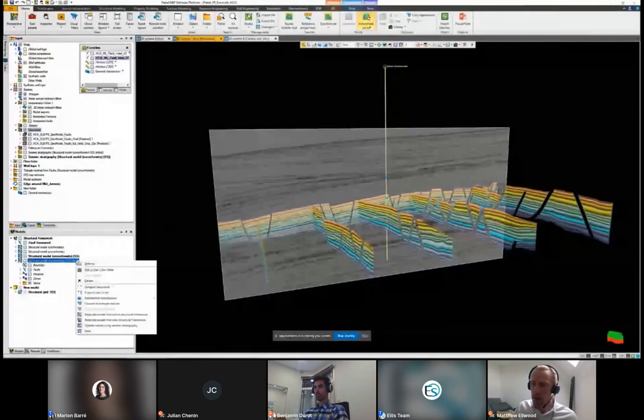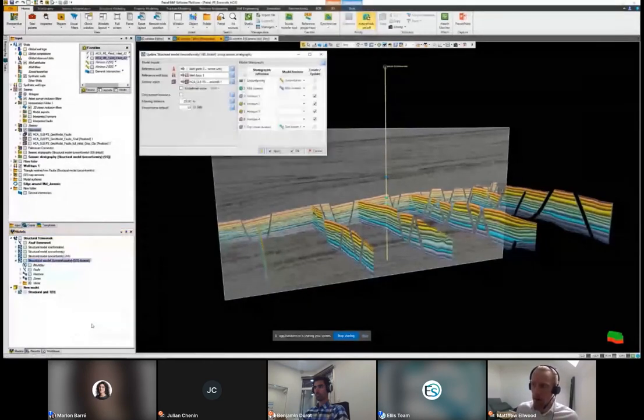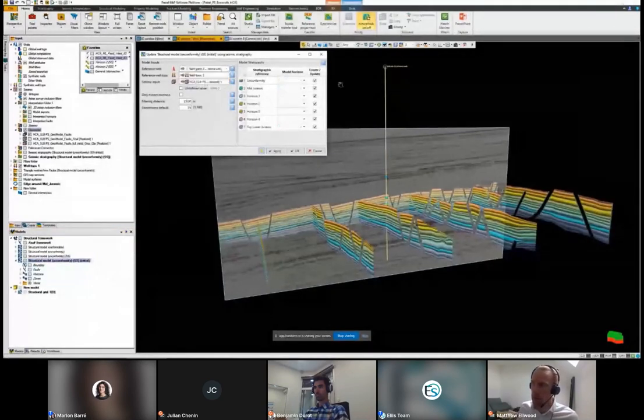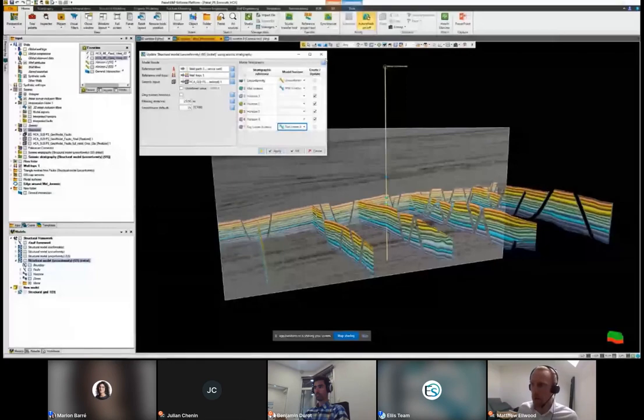And then using the new process called Seismic Stratigraphy, I can right-click on the structural model that I created initially to represent the main sequences. And within that, I can identify the well tops that correspond to existing horizons. And you can see here I've got additional well tops that don't have horizons in the model. So I'm going to extract 4 new horizons from the data and then automatically add them into the structural model and rerun that process. So here you can see I've pressed apply.